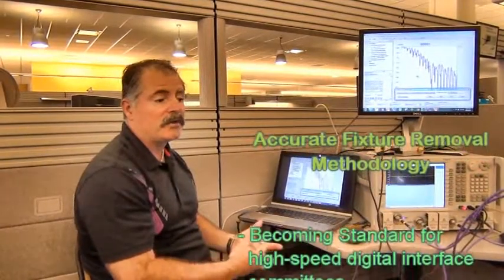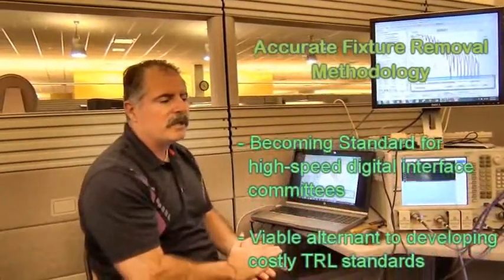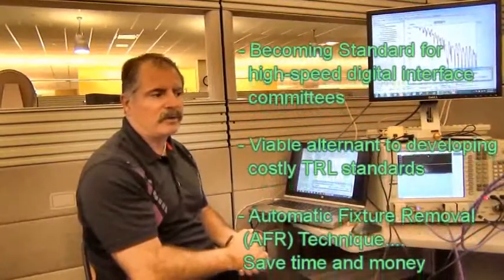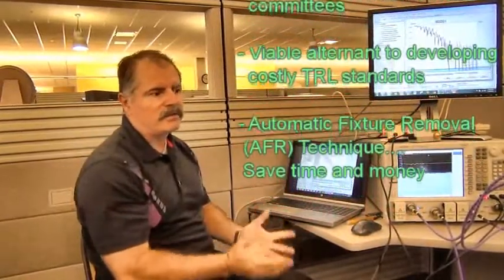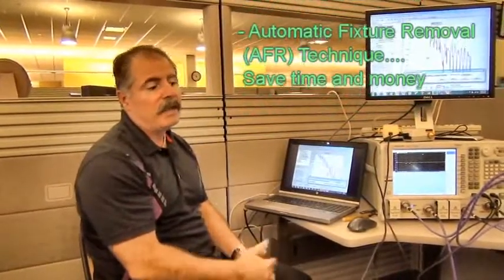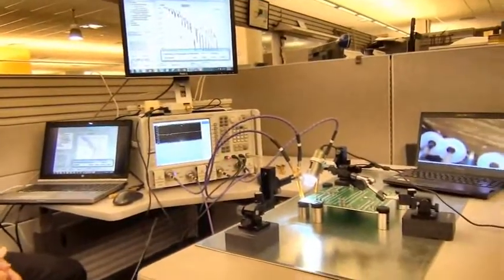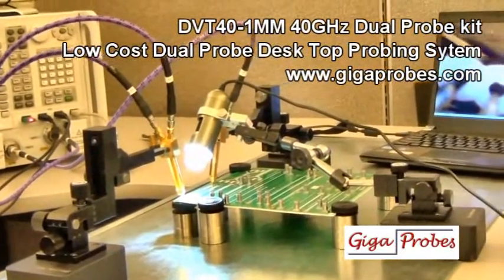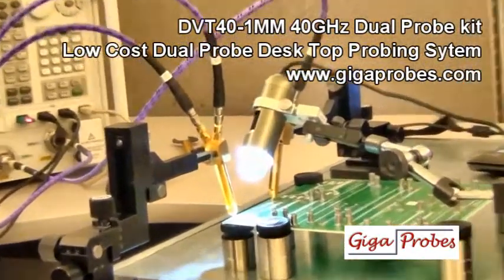It's becoming a standard in many of the high-speed digital interface committees. And so rather than struggling with through reflect line calibration kits, which require a lot of time and money, you can save a lot of time and money and use this newer automatic fixture removal technique. And the probing system for this does not have to be extravagant or sensitive or fragile. You can have a very robust probing system that allows you to make a wide variety of measurements in high-speed digital applications.